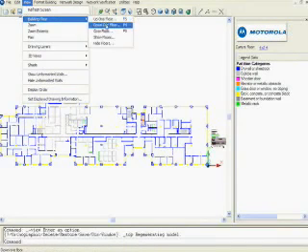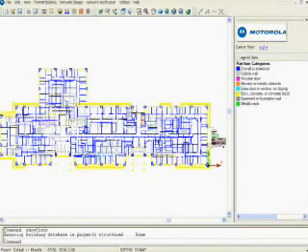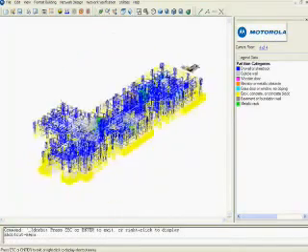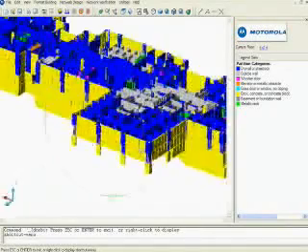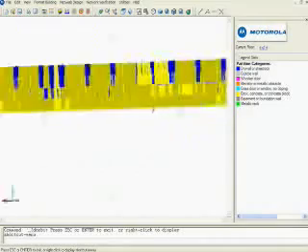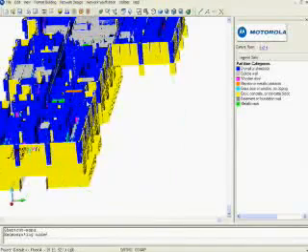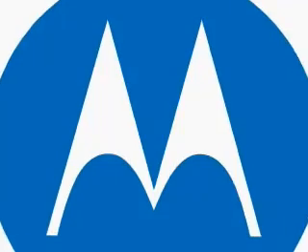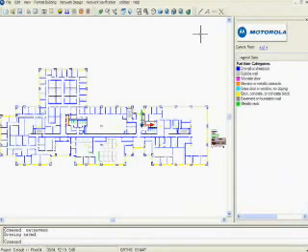If you have a building that has multiple floors, we can simply use the Show Floors function, show all of them at the same time, and then tilt the drawing in 3D. This 3D nature of the building is very important, as the LAN Planner tool allows you to visualize propagation between floors, so access point coverage and interference can be analyzed appropriately. Here you can see the building as we tilt it in 3D, and obviously all the wings line up. This is a very important step in the formatting process. Now we'll go back to a single floor view, and we'll tilt it in top down.